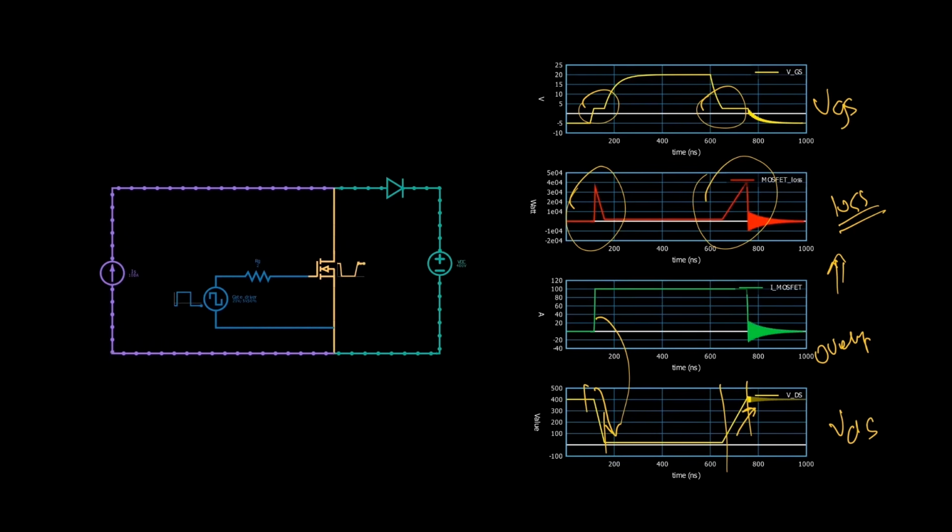So in this series of videos, we are going to deep dive into switching losses, understand the mechanism behind it for various circuits, and try to find out some mitigation measures that are usually deployed to reduce this switching loss. But for this particular video, we are going to focus only on the MOSFET plateau, the Miller Plateau, that it gets in its gate voltage waveform.